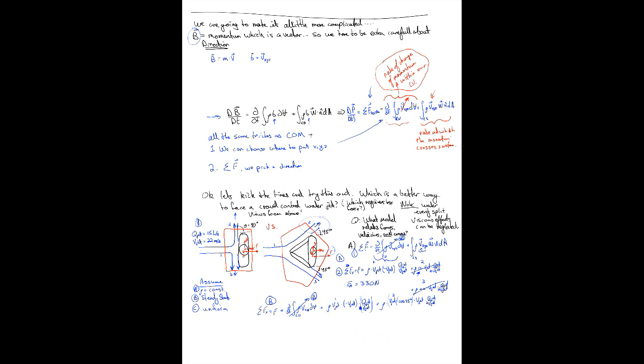For 3, our surface 3, which is our bottom exit, we're going to have a rho times v jet, and again, now we need to take the x component, which means we multiply that by the cosine of 45. And we're going to multiply that by our w dot n. In this case, our fluid is leaving our control volume perpendicular to our control volume surface. So it's going to be a positive 1 times our velocity, which is v jet.